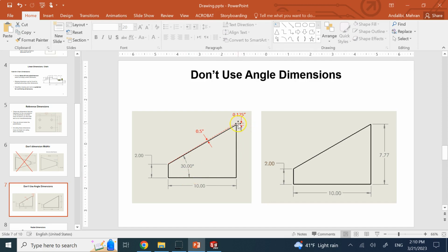Guess how much this tip point here will move? Well, because this is 10, it's not a small dimension, going from 30 to 30.5 makes this end point be up by about 1/8 of an inch. Right? And maybe that is way too much for my application. Maybe this endpoint can only change 0.01 of an inch or something. 1/8 of an inch is such a big thing, because this angle over this large distance will cause a big deviation.